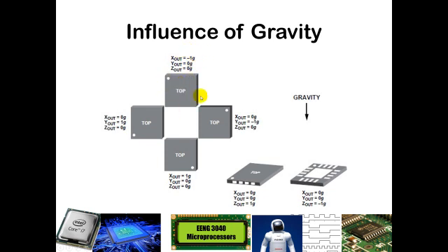If we were to rotate from this top position 90 degrees to the right, now the y-axis is the axis experiencing the acceleration due to the gravitational pull of the Earth. And so we can see 1g going downward here, as opposed to over here, if we rotate 90 degrees and 90 degrees again, a full 180 here, now the y-axis is experiencing that 1g in an opposite direction. If we lay the accelerometer flat, now the acceleration due to gravity is going perpendicular to the top and bottom of the chip, and so here we are seeing the z-axis experience 1g or negative 1g.